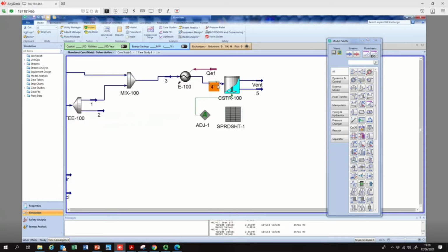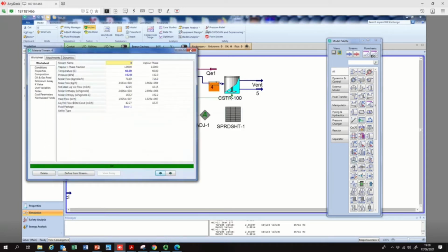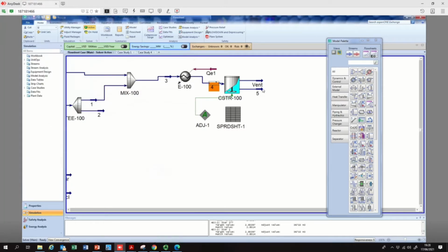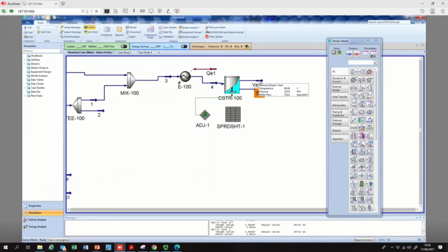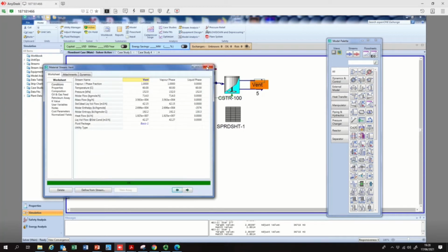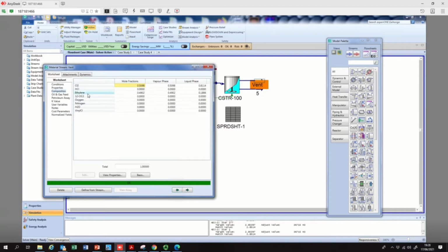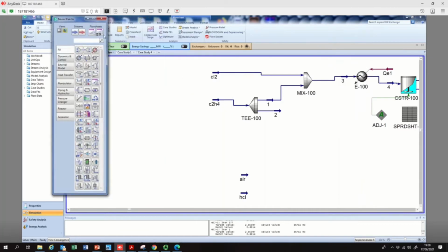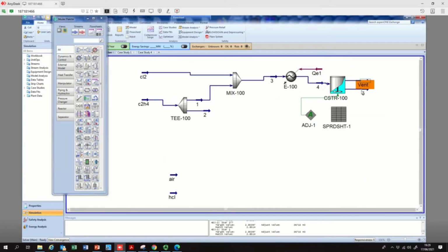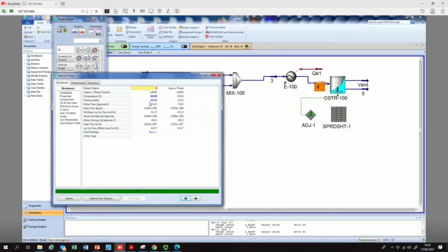So I think now everything looks fine to me. The flow rate is perfect. Vent looks fine. Composition, there is something with the rate expression that we took from the literature. 0.4902, 0.1186. If you listen to our lecture 2, what I said is we're performing this direct chlorination reaction at a temperature, I can double click on stream 4, of 60 degrees centigrade and 1.5 atmosphere.